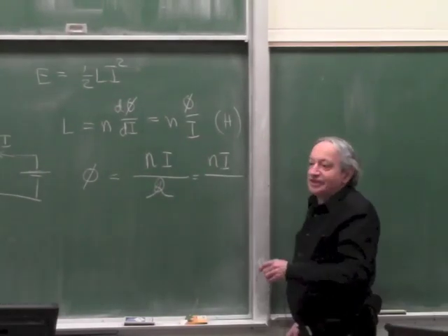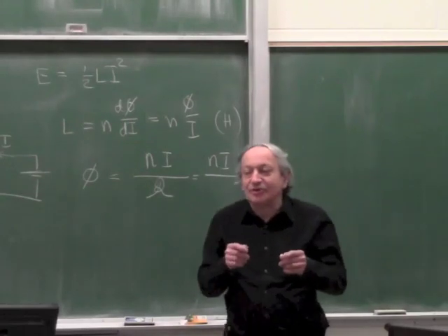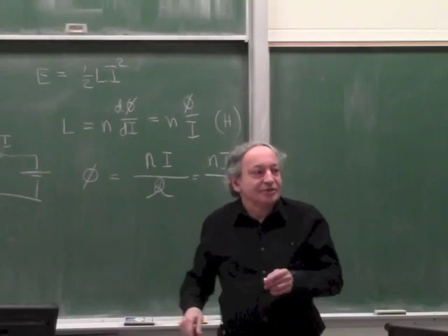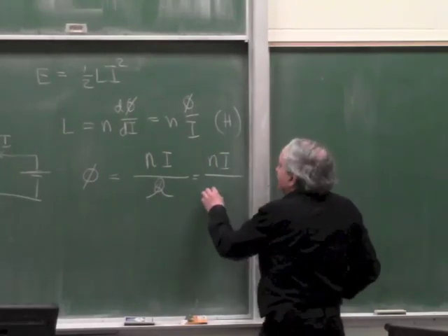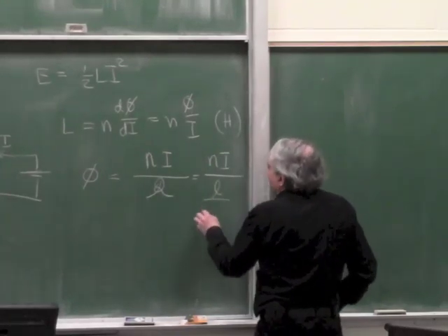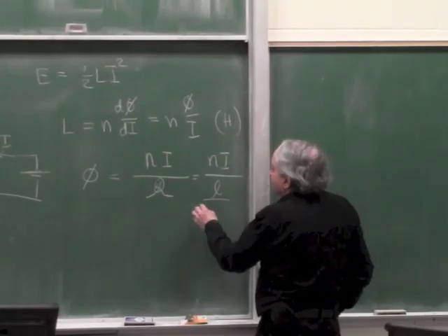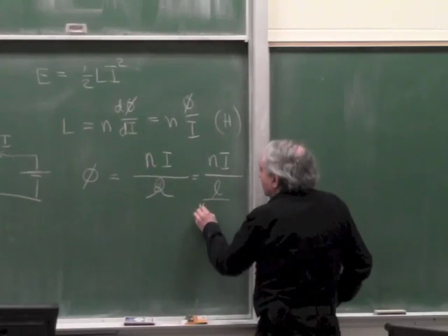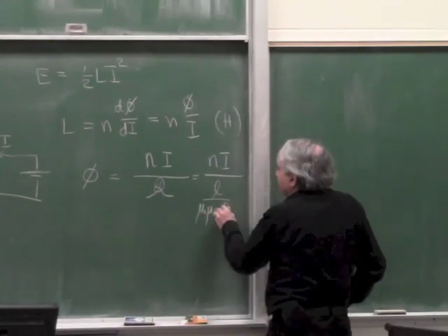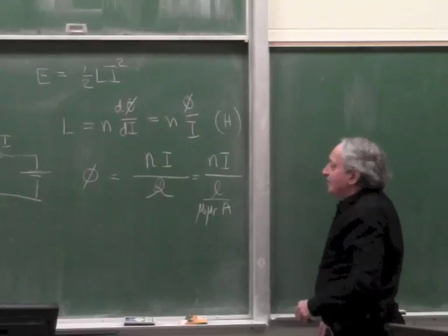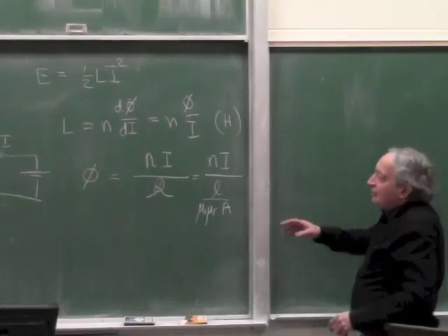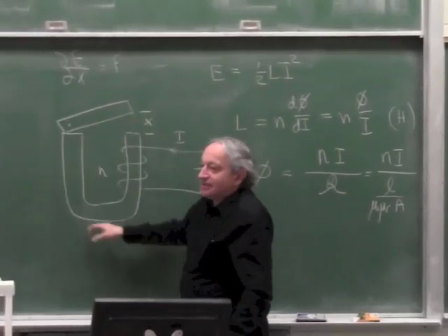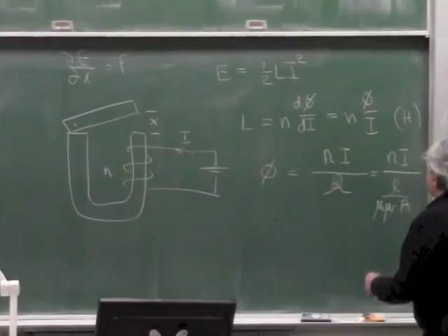In Ohm's law, resistance equals length divided by resistivity times area. So here it will be the same: length divided by, in this case, the magnetic conductivity, which is mu 0 mu r times A, where A is the cross section. Now, if you have multiple magnetic paths, a path in air and a path in steel, it will be the sum of all the reluctances.